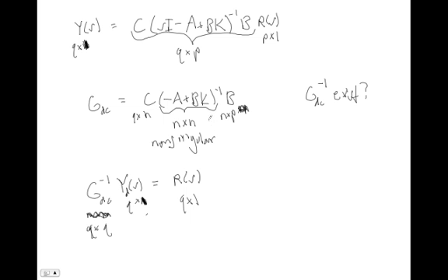And this comes down to, are you asking well-defined problems? So for example, let's say two of your states are position and velocity of some mass. Would it be reasonable for you to say, I would like my position to go to 5 and I would like my velocity to go to 10? The fact you're saying I want my position to go to 5 is the same thing as saying I want my velocity to go to 0. So if you ask for any velocity other than 0, it would be unreasonable for you to think that you could achieve velocity and position simultaneously.